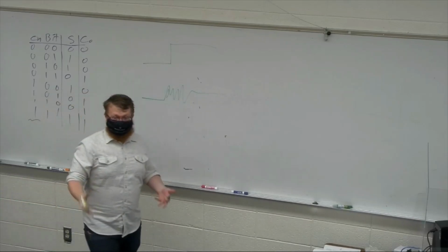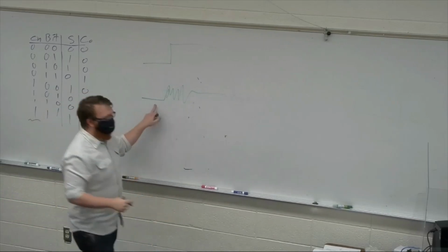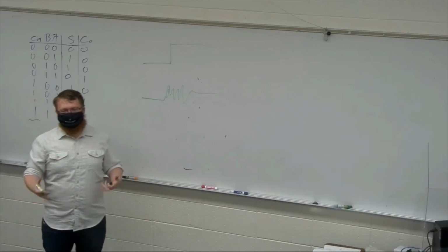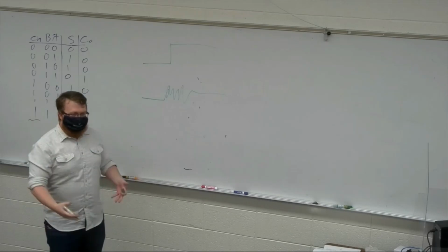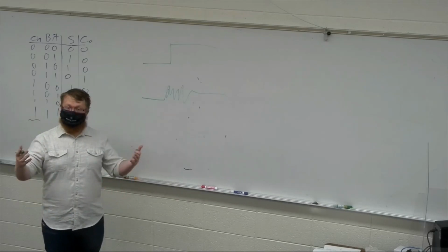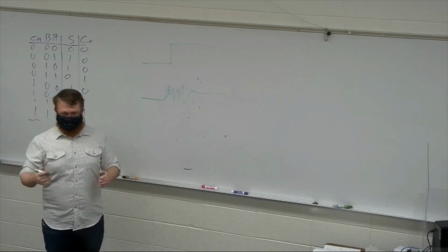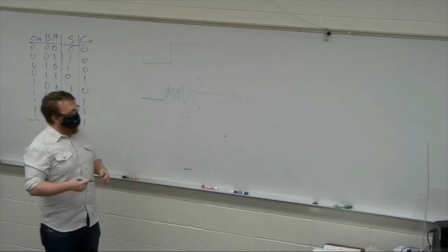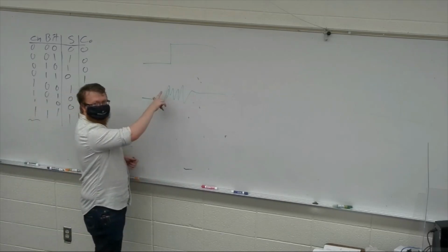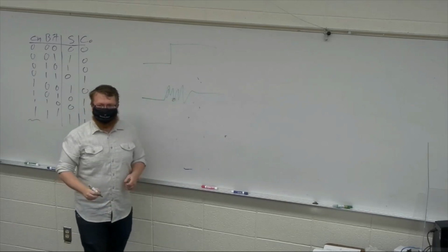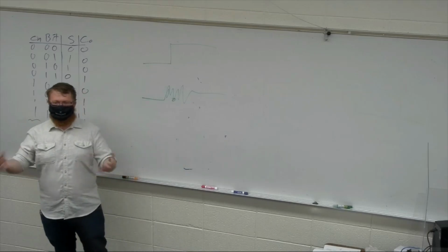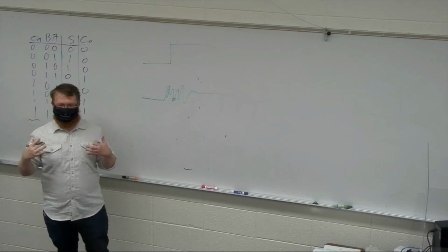So there's another issue. I push that, and I have a state machine that is watching that says, on the rising edge, add 1 to my counter if this button is pushed, right? So it sees a rising edge, and then goes, oh, let's take a sample, and then samples this. So it thinks it's trying to get a 1, but it really just got a 0.